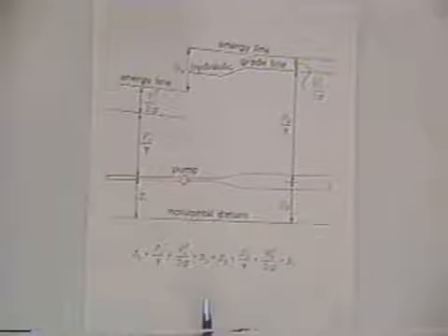So that's just the thing intuitively as far as pressures and heads in a pressure conduit system. And many of the problems that you solve are just a trade-off, as we said already, between the different forms of energy: the elevation head, the pressure head, the velocity head. And this illustrates some of the trade-offs, and it also illustrates that we can actually add energy to the fluid in the form of a pump. Head losses remove the energy, but we can also add energy in the form of a pump.